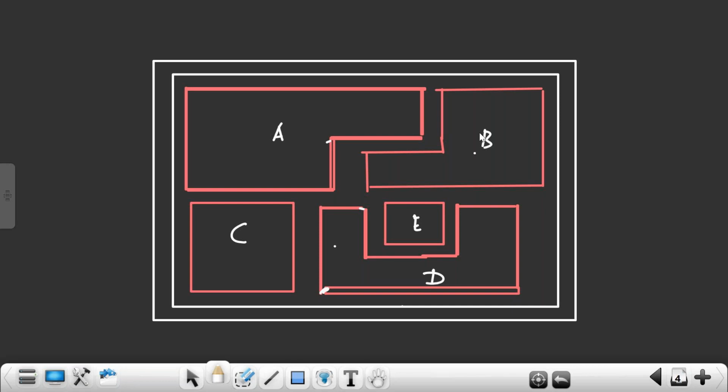You will do the physical design of each and every block level design. After completing the physical design for each and every block, your full chip designer will integrate all the blocks. They will make connections between all the blocks. He will generate a GDS file, then he will send it to the foundry. So this is called full chip level design.